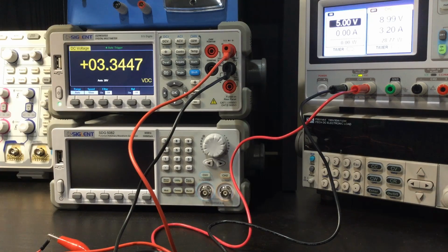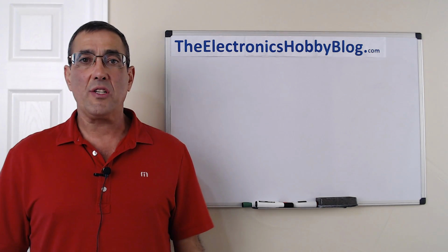And I'm just basically adjusting the knobs on this. That looks like it's as close as we're going to get right now. No, we can get closer than that. Close. See if I can hit it right on the head. So that's an example of actually tuning the resistors using the decade box. And if I read the decade box right now, it's set for 4943. So we're never going to find a resistor quite that size, but we could find a potentiometer in the 5K range.